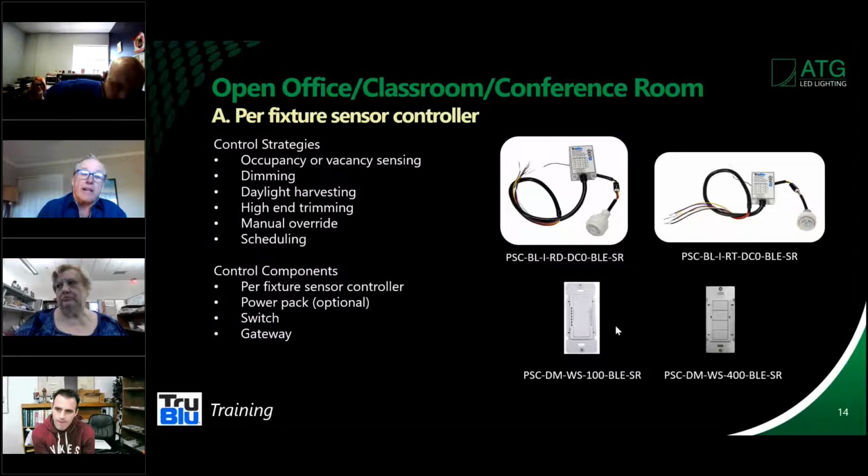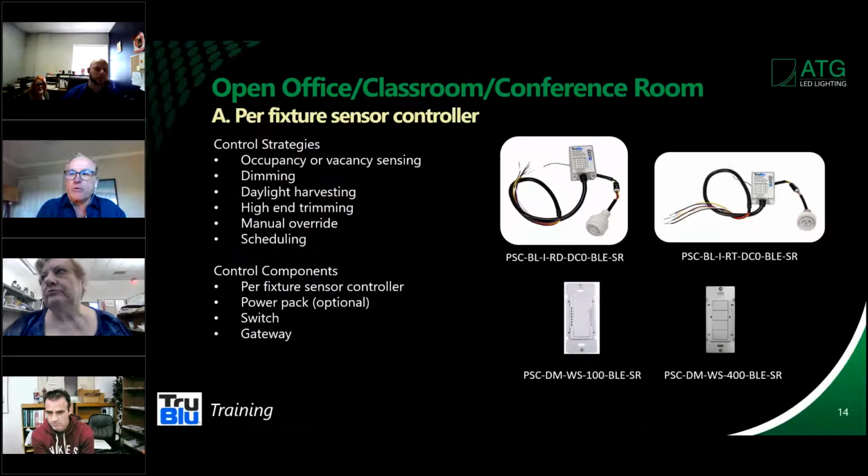Of course, the dimming. Now, daylight harvesting. The important part here is that this is true daylight harvesting. So this would be continuous fluid dimming. So even in a particular office area, you may have 2 zones, okay? You have the zone by the windows where we want to put the daylight harvesting sensors, and then you have the rest of the room that's reacting to that. So that's an important thing to understand. It's not just bi-level, it is fully continuous dimming. Of course, you have the manual override and the various control scenes.